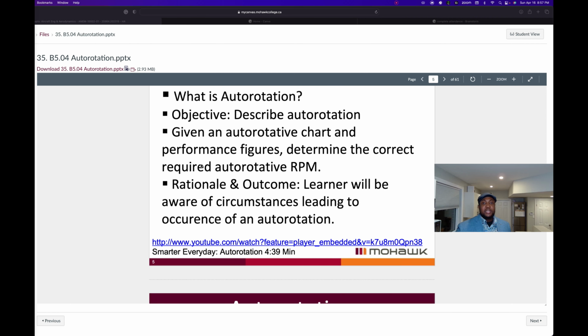In summary, we've described what autorotation is. We've talked about what freewheeling is. So freewheeling happens when the main rotor is disengaged. We talked about autorotative forces. We described the main rotor disc. The outermost portion is known as the driven region, which is not very useful to us, and it's about the outermost 30% of the rotor disc.